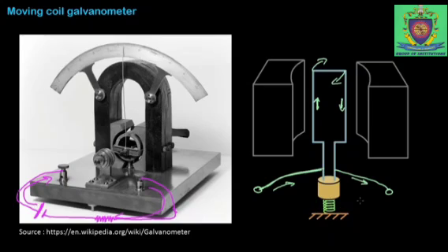This spring will have a restoring force. You know what a restoring force is from your first year. So this restoring force will also give a force. We know that the torque is created there, and here is your spring. From the spring there is a restoring force also created. So let me explain in detail. So this is your spring. For example, the rotatory motion is happening in this way. The spring's restoring force, with the support of a rigid support, will be in the opposite direction.